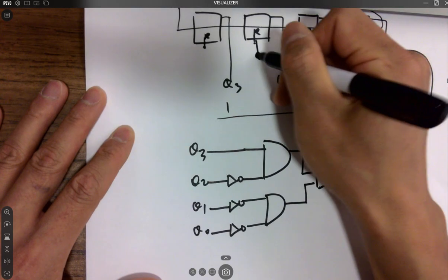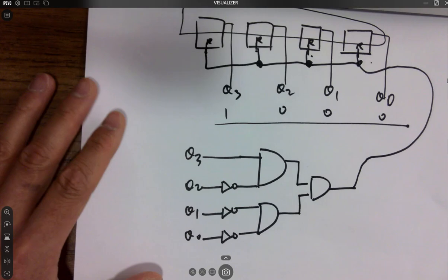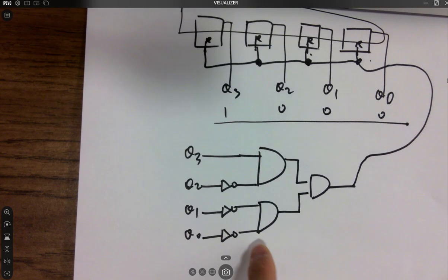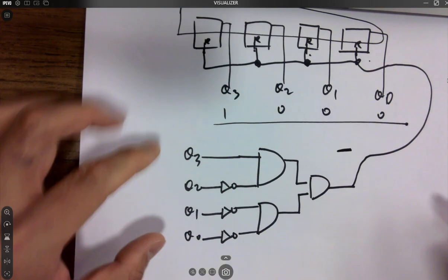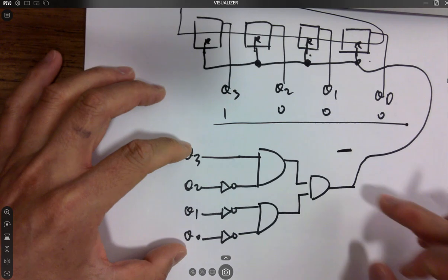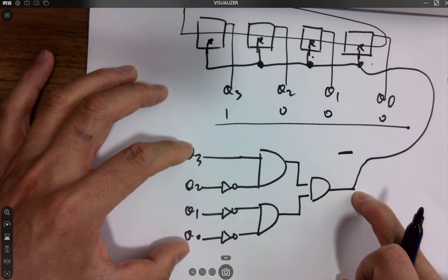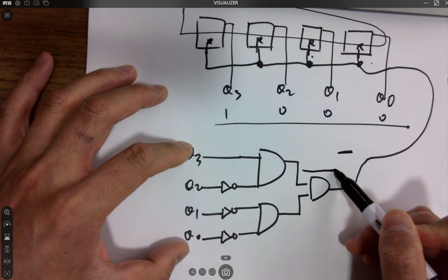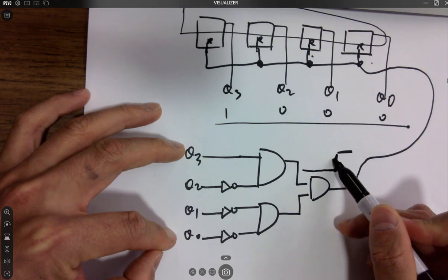Actually, no. All these are AND gates. You need all ones to have a 1 here. For any other code, it will be 0. Do you agree with that? Which means it's going to be 0 for a long time. Whenever it hits 1 0 0 0, boom.